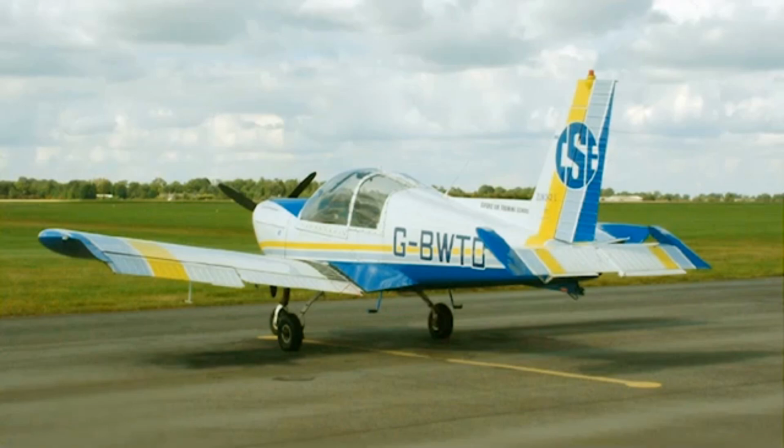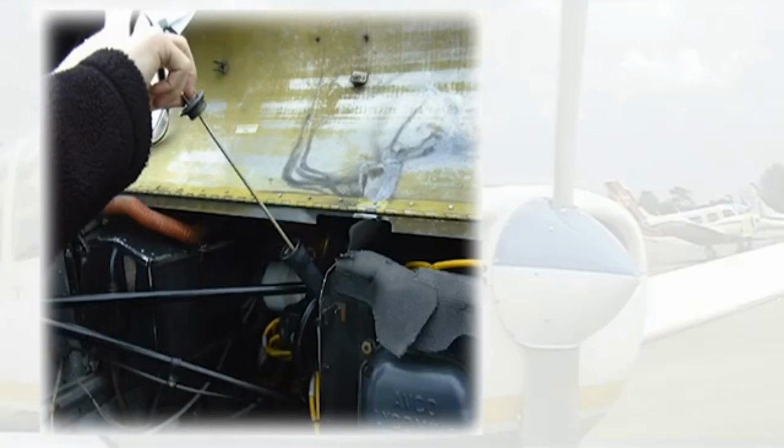If the aircraft you are operating has a dry sump engine, then its oil contents must be checked immediately after the engine has stopped, realistically within a few minutes of shutdown. This ensures that the tank contents are recorded accurately before the oil migrates into the sump under the influence of gravity. If, on the other hand, the engine has a wet sump, then a period of 15 to 20 minutes must elapse before the contents are checked.